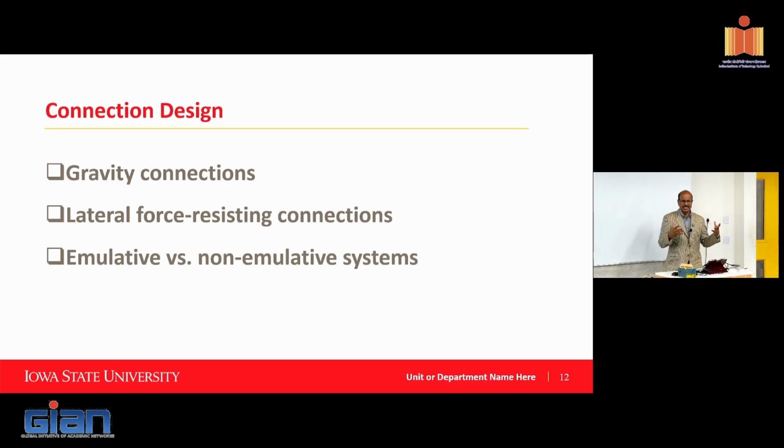So for emulative connections, people have come up with different ideas. We'll go through them. The non-emulative connection concept is to take advantage of the precast product features and design connections so that it doesn't really try to behave like regular concrete.